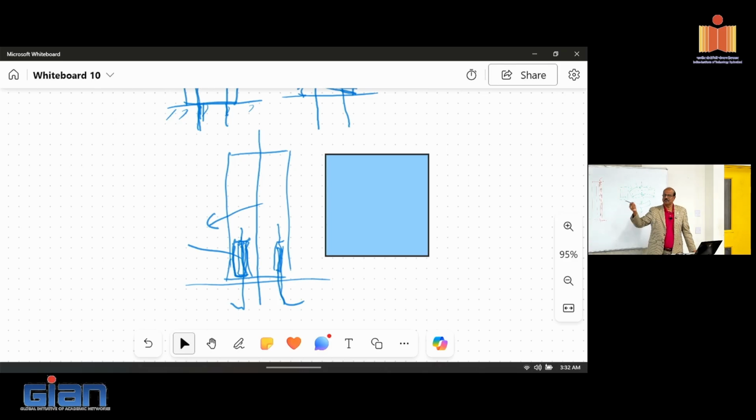The second concept that I presented is what's known as a jointed connection, taking advantage of the features of precast. What is best for what we know is where the joint is, and we would allow it to develop gaps right at that location, where the actual disturbance is between the continuity from foundation to the column, for example.